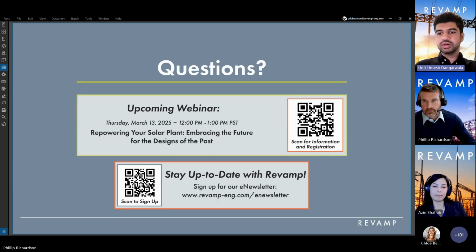Does ETAP consider inverter contribution during incident energy calculations? As a contribution from the inverter will be cleared within 0.16 seconds for 50% under voltage. How does anti-island of inverter affect incident energy during faults? So yeah, we've had extensive conversations with ETAP regarding inverter contribution for arc flash analysis.